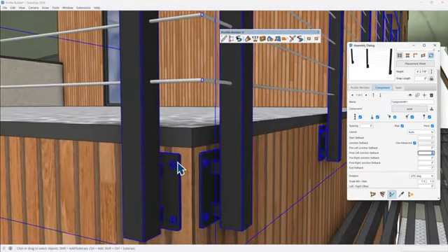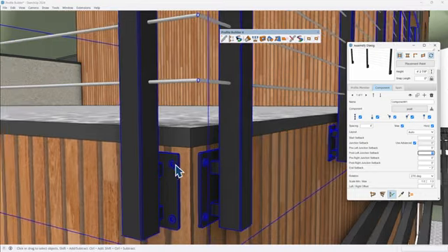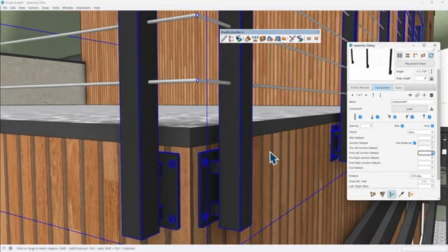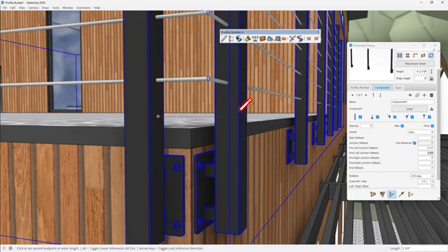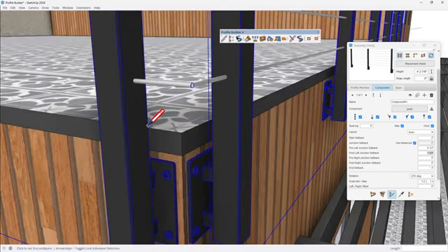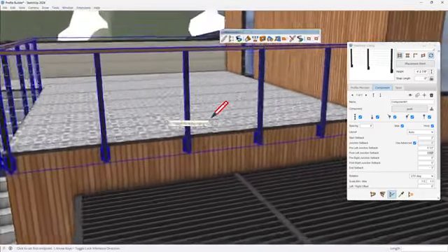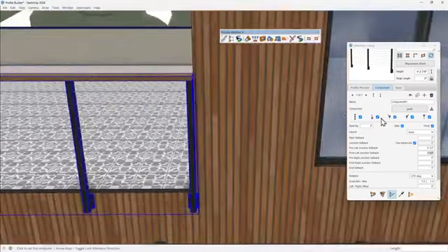And this is where if I had more control and defined the parameters of this, it would show up a little bit better. I want to get this just a little bit tighter. So I'm going to do 4.5 and I'll do 0.5 because I want to make sure that there's not more than 4 inches between each piece. And right now I'm exactly at 4. So that's good.